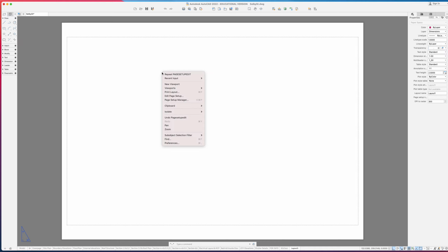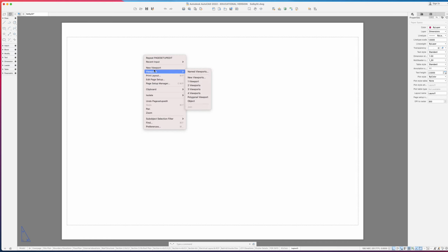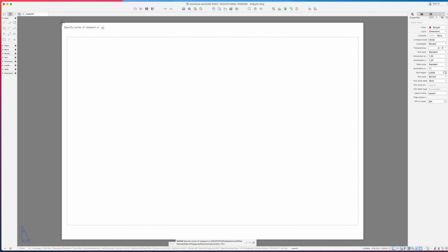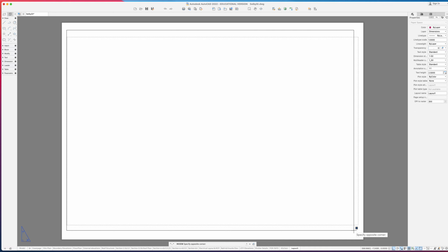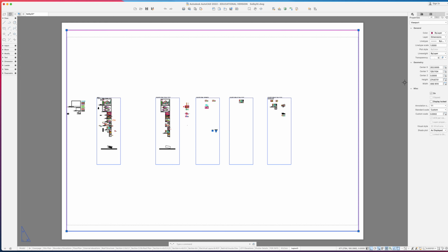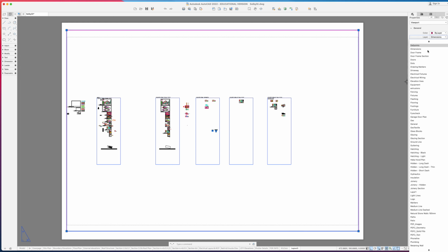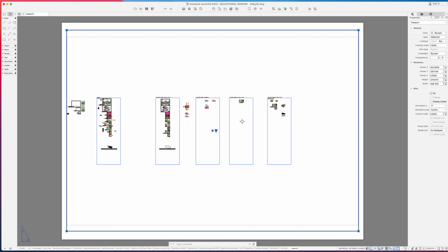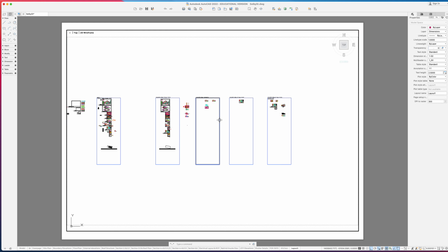I don't need a title block and a legend and notes because I'm not adding that information. This is for rendering purposes only. So then I'm going to right click and say new viewport, and filling most of the page I'm drawing a viewport, and that viewport we always pop in the def points layer so the line at the edge of the viewport doesn't show up. Double click to activate the viewport. We know it's activated because the border of our viewport becomes heavier in line weight, and then in our status bar in the bottom right we see additional scale options.